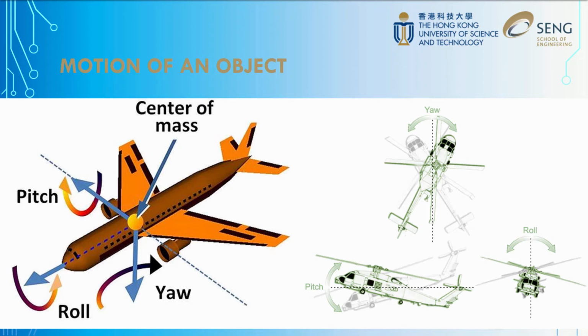That said, identifying the location of the mass center is always the first step in mechanical engineering design. In practice, you can always use a finger or a string to test out the balance points and thus the center of mass of your prototype quickly. And this is very important in the exercise. Try to do it as frequently as possible to give you a better understanding about where the center of mass is, and then use it to predict the motion of your prototype.